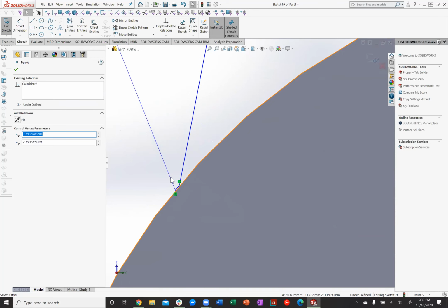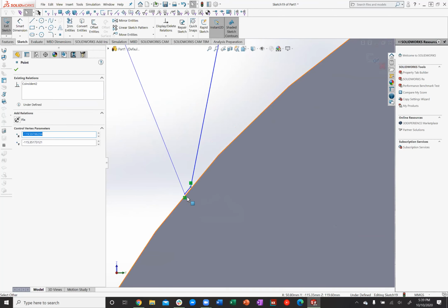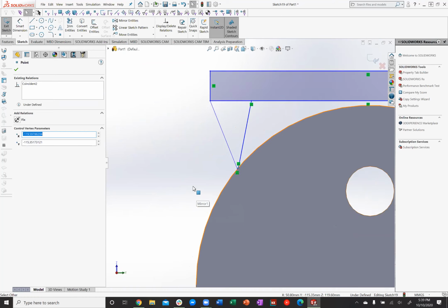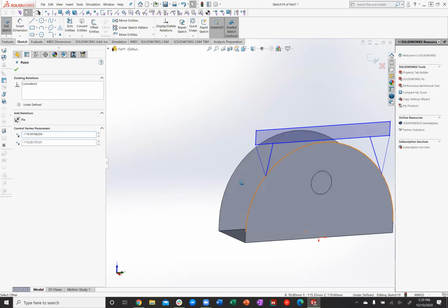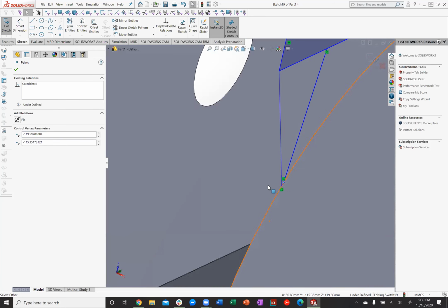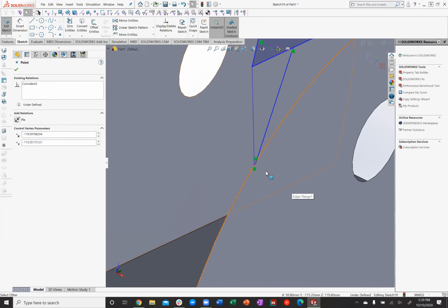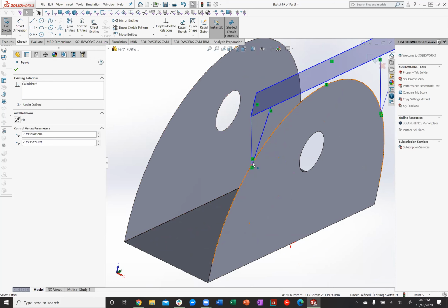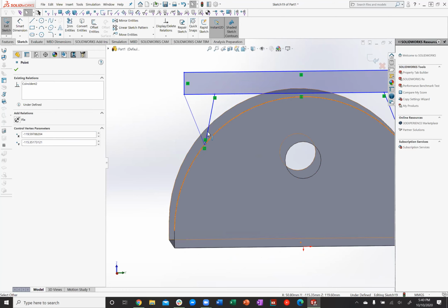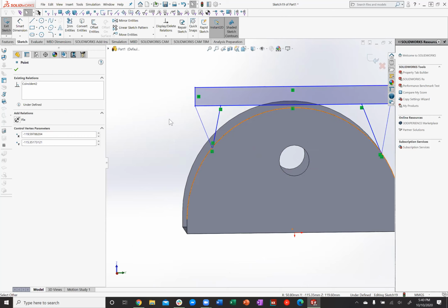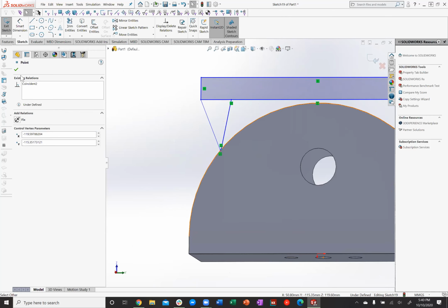All right, so this is material here that touches. It doesn't have to be very big. It could be as thick or thinner. Actually, yeah, much thinner than the material if it's a thick material. I would say like a 1/32 or 1/16, just a point basically touching so that you can break this piece away after.